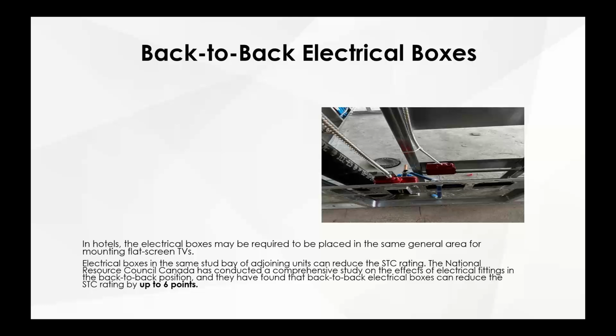You're building your wall. You provided a sound report to the owner. You're building it to it. And then all of a sudden, you've got all these penetrations in there. You need to speak up and ask about this because what you probably provided in your submittal package didn't have all these boxes and penetrations in there. So let them address it.